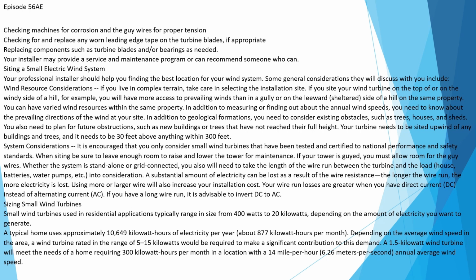System considerations. It is encouraged that you only consider small wind turbines that have been tested and certified to national performance and safety standards. When siting, be sure to leave enough room to raise and lower the tower for maintenance. If your tower is guyed, you must allow room for the guy wires.